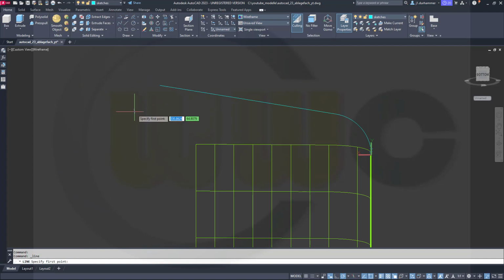Again, I need a line to trim it. This one should be at 240 column 0 and go straight up here. Now go for trim, select them both, right click and remove this one here and delete that line. So this should be a polyline, so go for P-edit, go for multiple, select them both, right click, convert, yes, join, fuzzy distance 0, enter, and this should be a polyline.